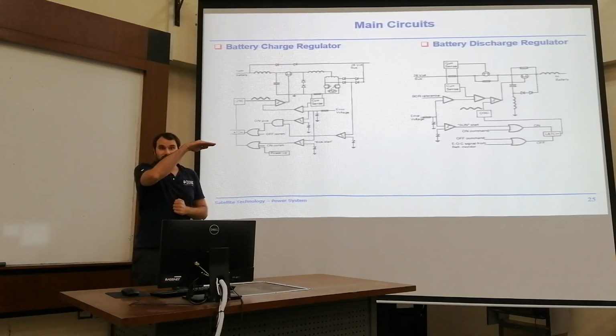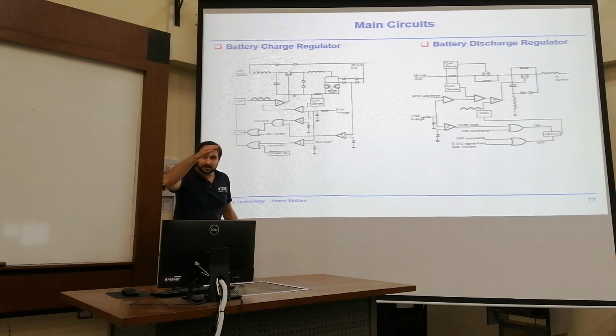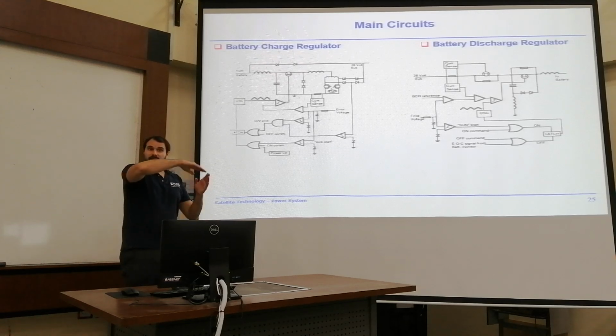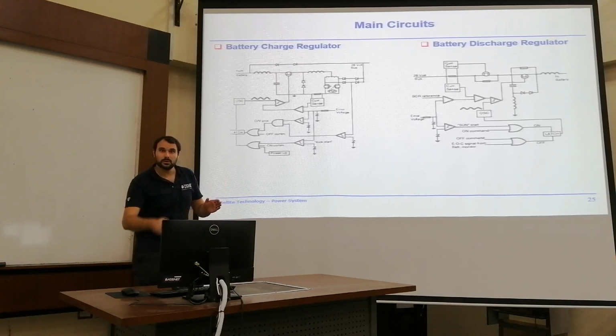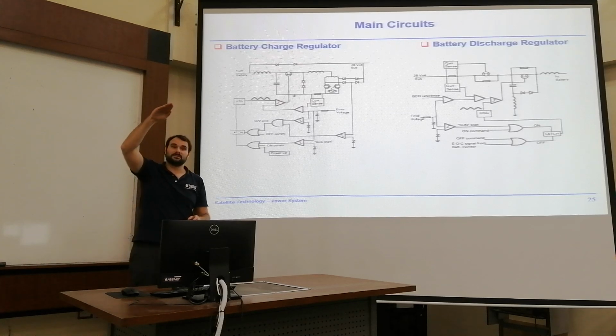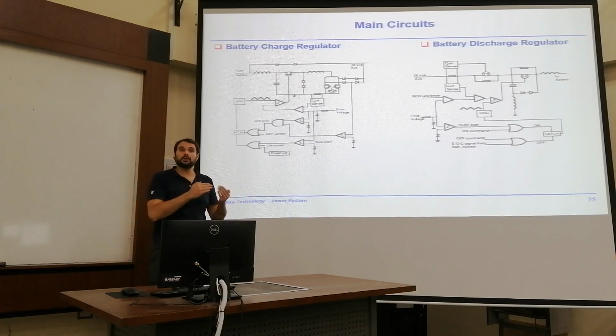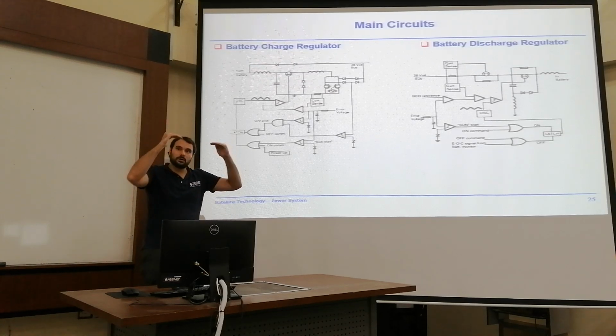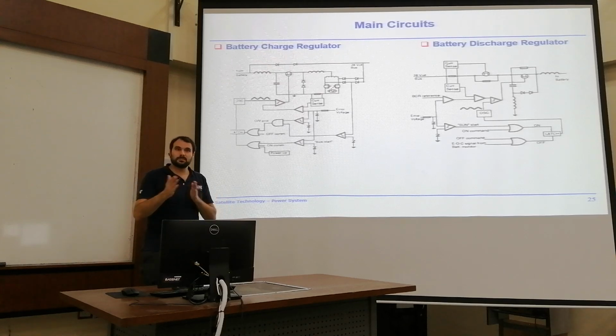Then you discharge your coil, so all the output is fed by the coil, and it decays. But instead of letting it decay to zero, you switch it back on and recharge. By dynamically switching on and off, you can decide where you want to land with your voltage level, simply by the duty cycle of being on and off.